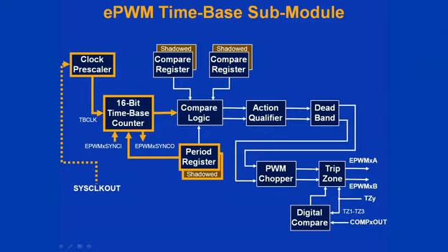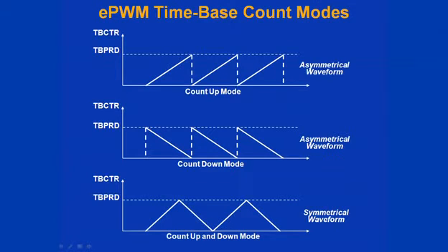Additionally, the time-based counter has the capability to be synchronized and phase shifted with other EPWM units. The upper two figures show the time-based counter in the count up mode and count down mode. These modes are used to generate asymmetrical waveforms. The lower figure shows the time-based counter in the count up and down mode. This mode is used to generate symmetrical waveforms.